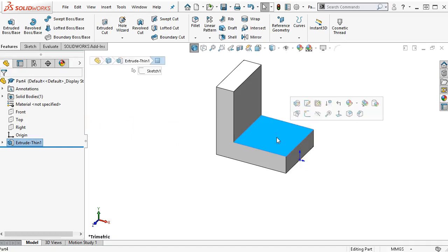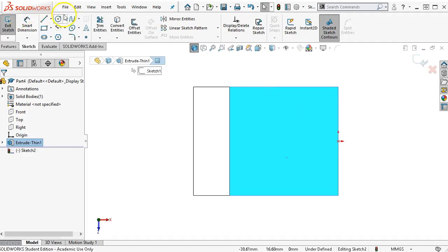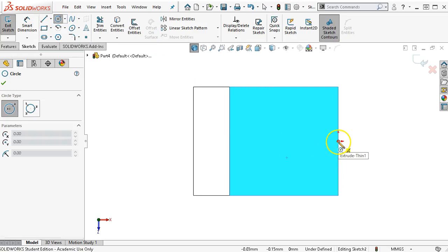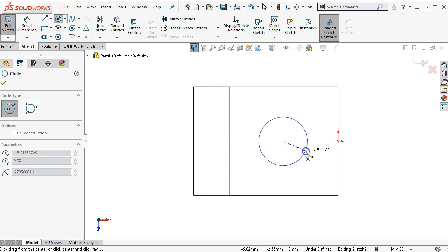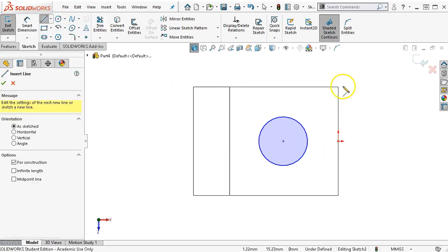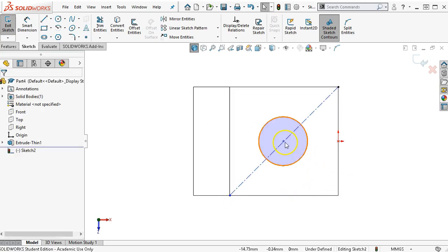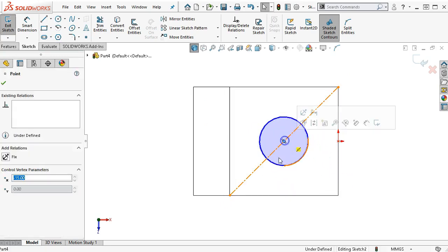And then for the hole locations, let's see, it's 15 millimeters in and 15, so we could say that the through holes are centered on those faces. That might get us into trouble later, but I shouldn't have to make too many changes here. So one option would be to center line. I kind of prefer the corner to corner.